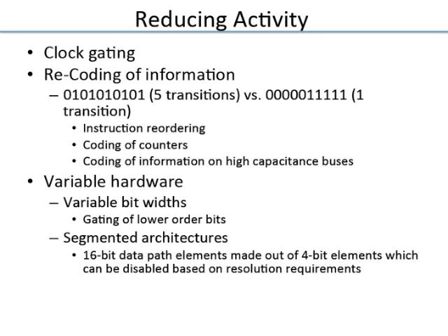One popular place where this is used is instruction reordering. You have a memory from which you fetch instructions, and the instruction, maybe a 32-bit instruction, comes out from the memory, goes on the instruction bus, and comes to the processor. So there is a sequence of instructions, but maybe you look at the sequence and say, instead of I1, I2, maybe I do I2, I1, provided your processor and your program are able to deal with that. Sometimes the instructions don't have dependencies, and they could happen in any order. So why not use the order which will minimize the transitions?